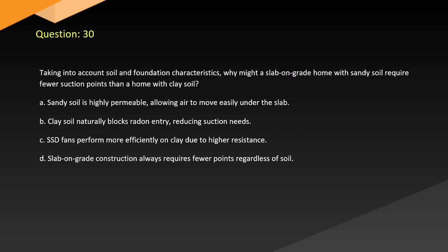Question 30. Taking into account soil and foundation characteristics, why might a slab-on-grade home with sandy soil require fewer suction points than a home with clay soil? A. Sandy soil is highly permeable, allowing air to move easily under the slab. B. Clay soil naturally blocks radon entry, reducing suction needs. C. SSD fans perform more efficiently on clay due to higher resistance. D. Slab-on-grade construction always requires fewer points regardless of soil.